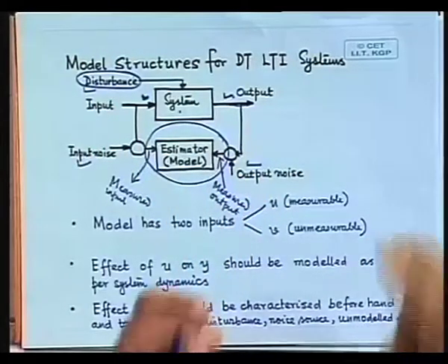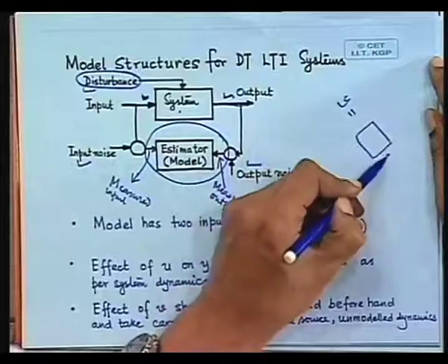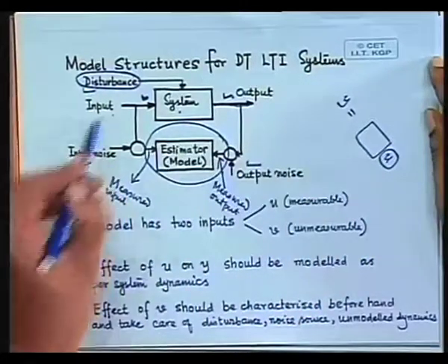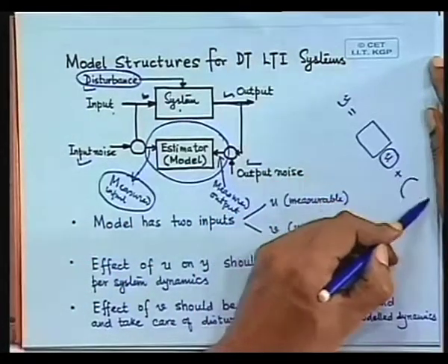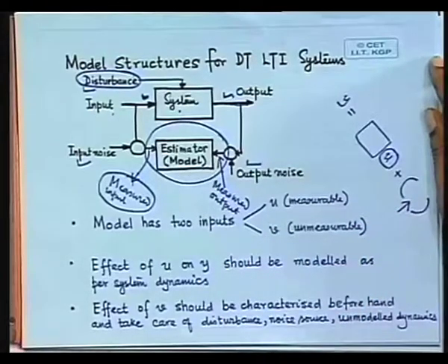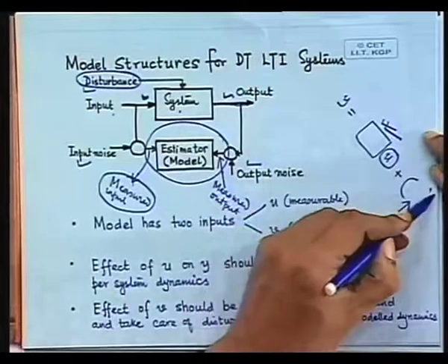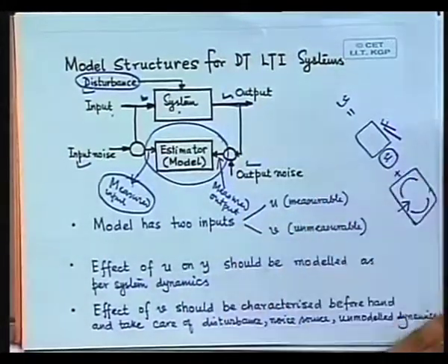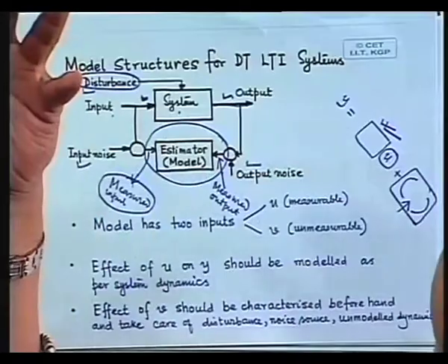So basically what you do is, in your model you try to say y is equal to some function of u, which is your controlled known input, this one that you use, plus whatever is the rest, you say that is some noise term, and you want to characterize that noise term. That means you have to choose such a model, so when you are trying to estimate, you have to choose what kind of thing is this, what structure is this, and you have to choose what is the property of all these that you have not modeled, and all these that you have chosen to describe by the term noise. Now, what is its characteristic?